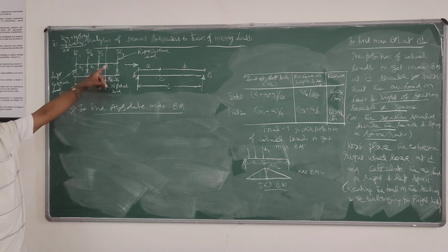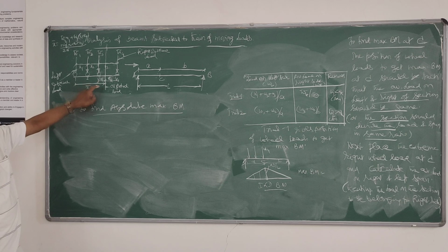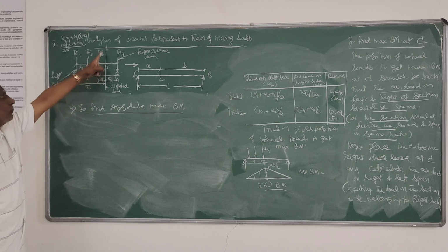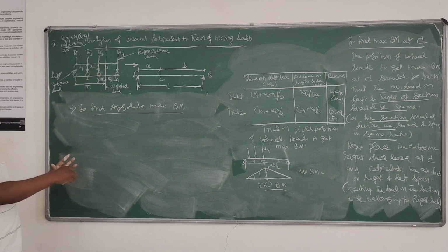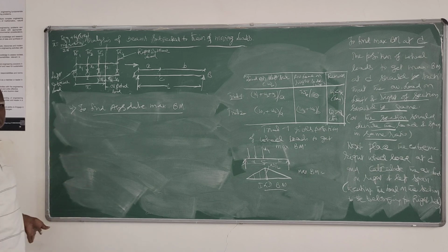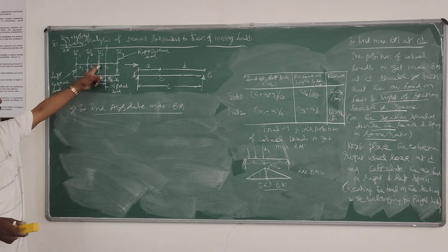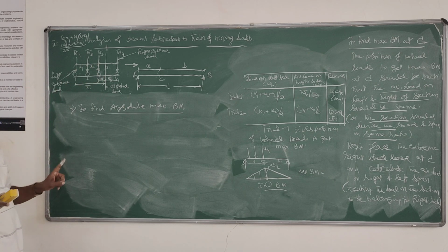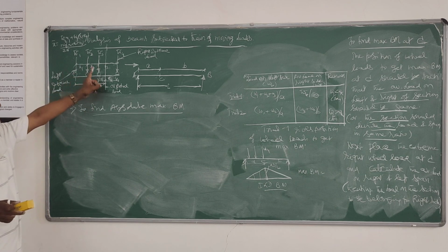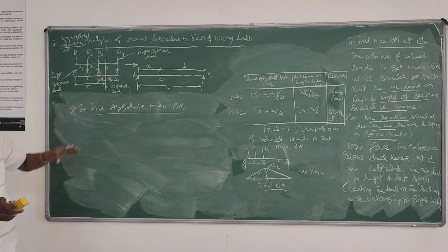Otherwise, better to take both the loads closer to the CG line, and you place that CG line symmetrically about the center point, at the same distance from the center point. You calculate the bending moment under the load, not at any point on the beam, under that particular load, either W3 or W4.